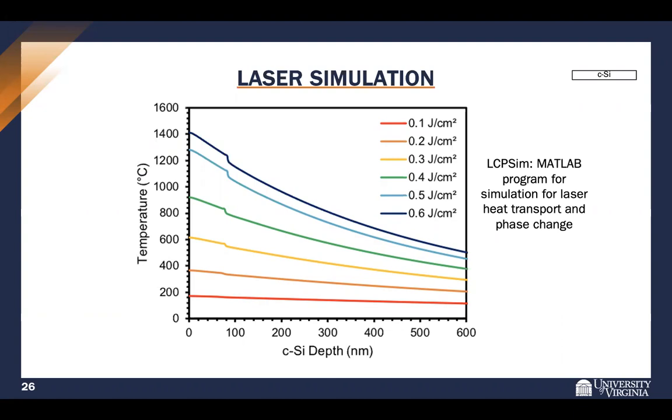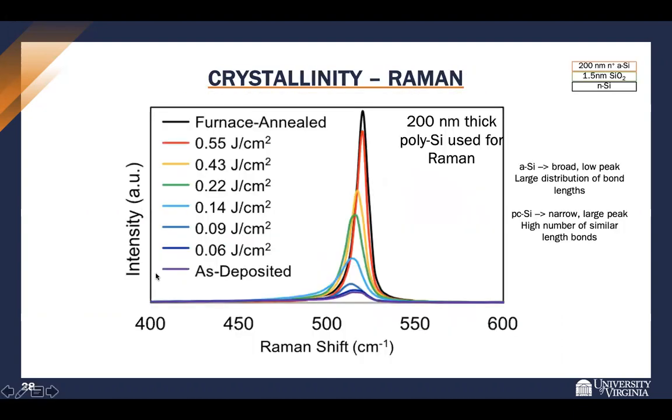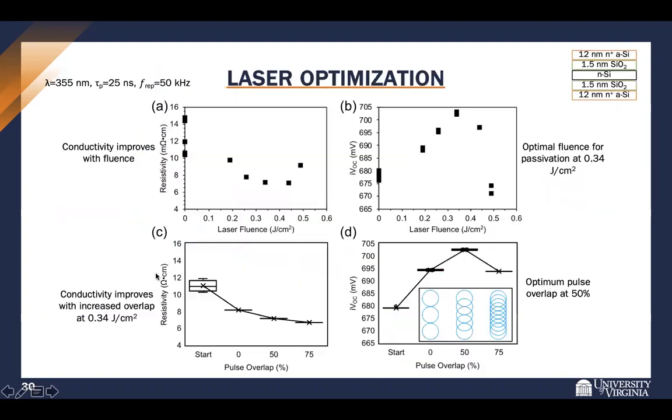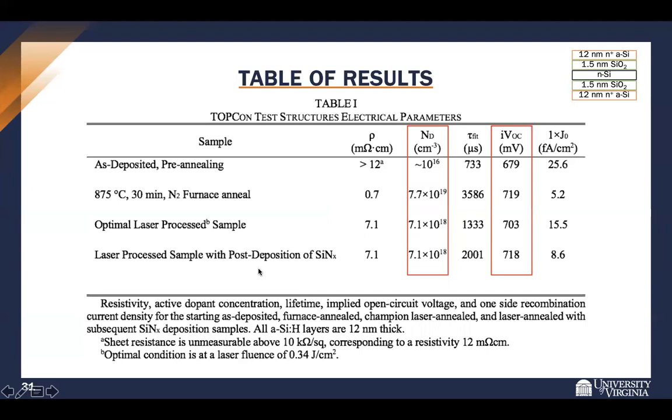All right, thank you. Another question I had was, if you go to slide 28, I think it was 28. No, I'm sorry. If you keep going, there is a table of performance here. So you got a much better result after depositing silicon nitride. What does the silicon nitride layer do? It'll improve passivation. At this thickness, I use a 60 nanometer film. It'll act as an anti-reflection coating a bit, so that'll allow for more light capture. But it seems to improve the passivation as well, even though you're depositing silicon nitride on the outermost layer.